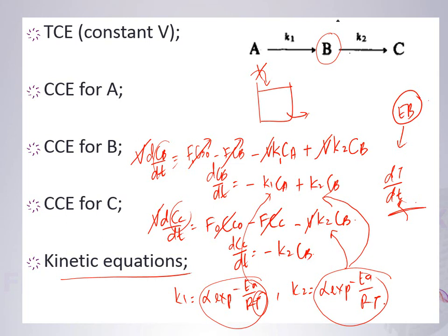Because when the reaction starts to occur, for example a polymerization process, it is an exothermic process, so the temperature keeps being released. So when the temperature is released, what you have to do is bring it down to a constant point, but it has to gradually decrease to finally stop the reaction. Even though you quench it, it initially has a certain temperature, and then you quench, you put in like minus 20 temperature, still it will have to take time to come down.